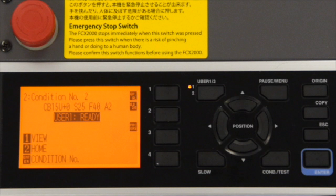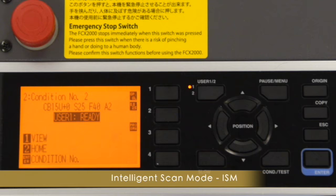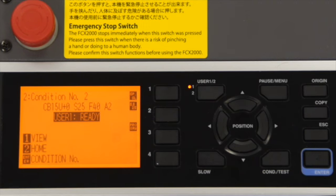The last function we will discuss provides better accuracy when scanning registration marks. Intelligent Scan Mode, or ISM, helps the scanner detect marks on harder-to-read media such as lamination, high gloss, and reflective by using a more extensive search algorithm.